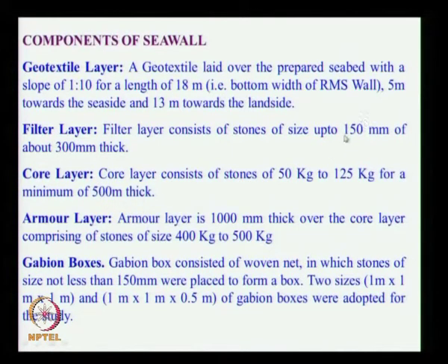Normally if you use size of stone 150 mm, twice the size of the stone we have to put the thickness of the filter layer, at least twice the thickness of individual material should be there. Here if you are putting 500 mm thickness, the average size of this 50 kg to 125 kg stone will be 250 millimeter. Then armor layer is 1000 mm, this over a core layer of stones 400 kg to 500 kg, the approximate size will be about 400 millimeter or so. So twice the size we have to provide this.